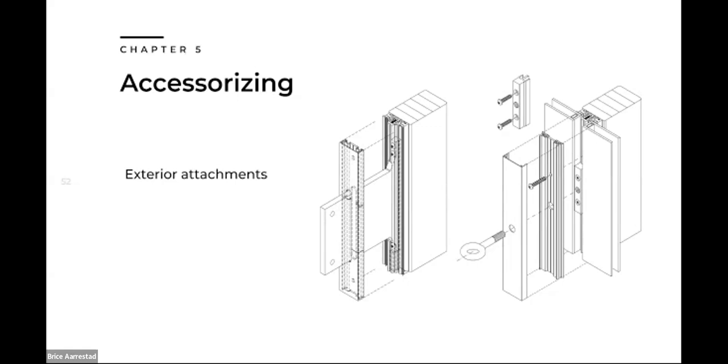And so those lateral forces will need to be accommodated in the design, either through thicker timber mullions, so wider sight lines, or in the way that those timber mullions are connected and tied back to the system. Some of those loads can be taken up in the anchoring devices and then applied to the building structure. So additional coordination is necessary if you're getting into those kinds of options, but certainly doable.